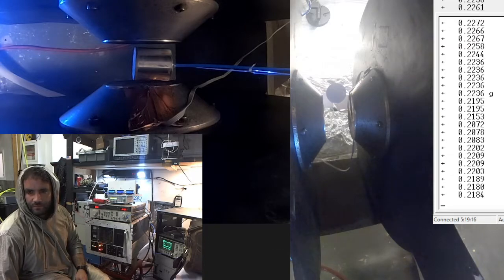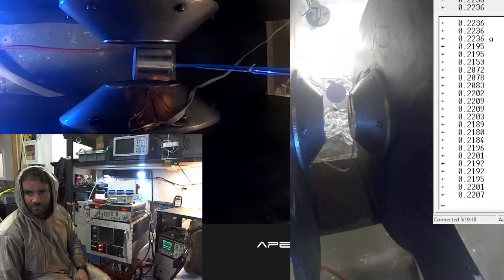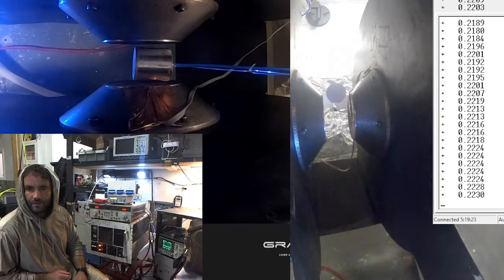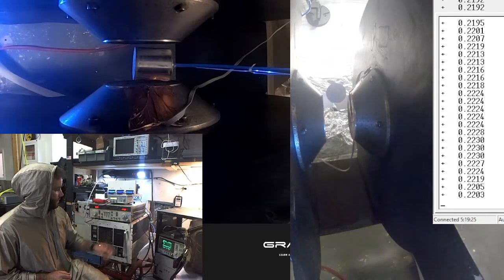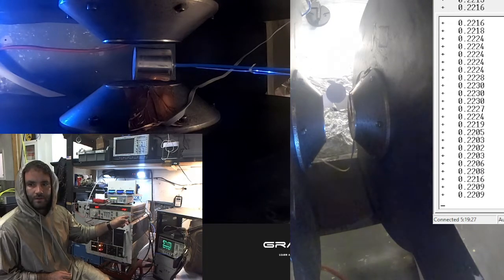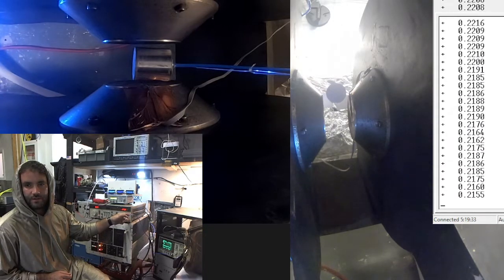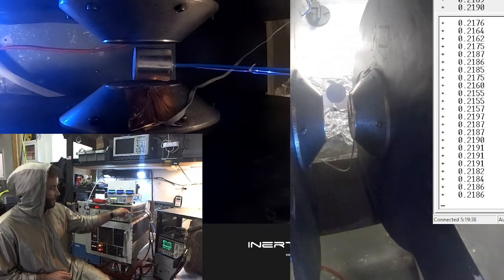All right, do me a quick favor. Put your hand behind there, grab the RF cable that's coming out of that SIG gen, and I just want you to wiggle it left, right, up, down by at least a quarter inch. I'm not asking you to wrench on it. Just fluctuate it around a little bit. I don't want you to shake it. I want you to just simply press on it and hold it for about 1 second in each position. I just want to see if there's something.